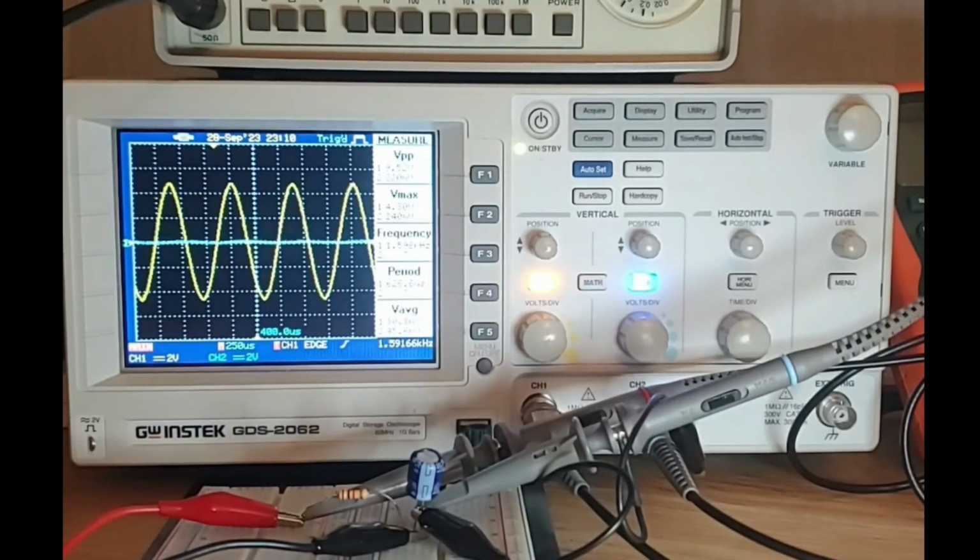And that's why you would sometimes hear that the capacitor is actually a short circuit for high frequency or for AC. So the capacitor is open for DC, but for high frequency, it's a short circuit. So that's why the capacitor voltage is almost 0.